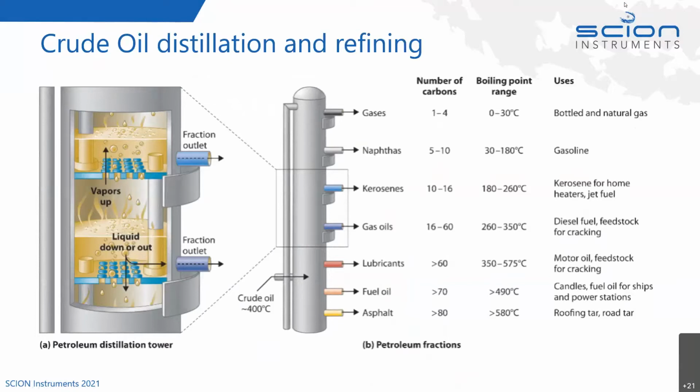So before we can get our gasoline, our petrol, or diesel, the crude oil is taken to an oil refinery, arriving in ships, super tankers, pipelines, and the refiners will process the oil to produce the petrols, the diesels, the oils. The first major processing unit on the refinery is the crude oil distillation unit. In simple terms, the crude oil is piped into a gas oil fired furnace, heated to about 400 degrees Celsius, and then it's piped into one of these distillation columns shown here. These are tall steel structures, easily 50 meters in height, with an arrangement of metal pipes inside.